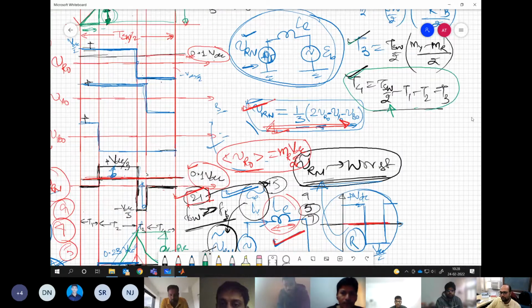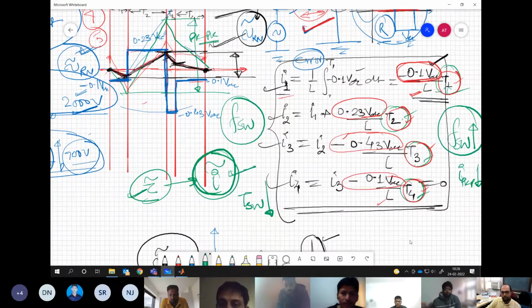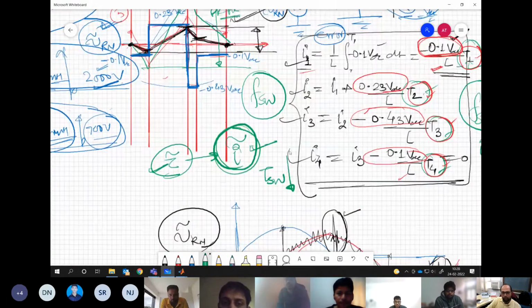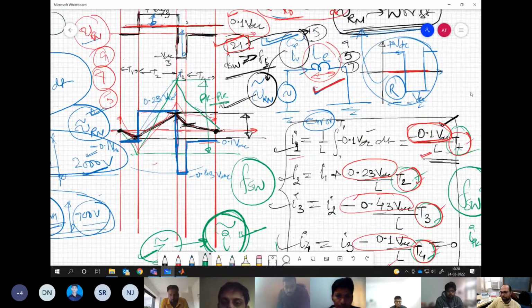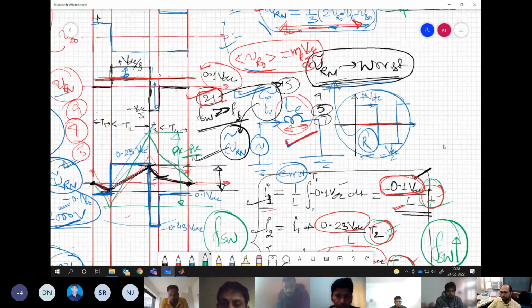Yes, sir. Now once we have computed, we can identify the place where we are going to have the worst ripple. Worst current ripple means the place where we are having the worst voltage ripple. And we will encounter the worst voltage ripple wherever we are not feeding any actual voltage but still applying PWM. That means at the zero crossing of R phase voltage.